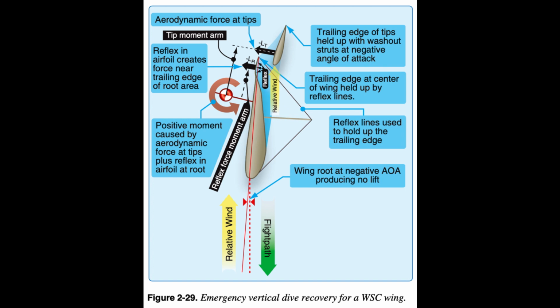Carriage moments. The wing design is the main contributing factor for pitch stability in moments, but the carriage design can also influence the pitching moment of the WSC aircraft. For example, at very high speeds in a dive, a streamlined carriage would have less drag and, therefore, a greater nose-up moment because of less drag.